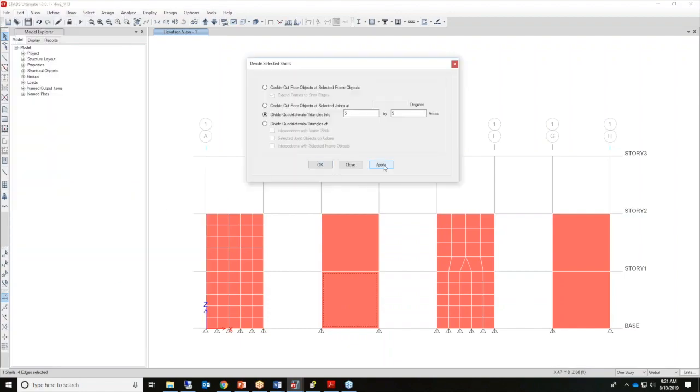And I'll do the same for this one, but I'm going to make a little bit of a change here on top. I'm going to make this 4 by 4. So here we have a situation with some mismatched nodes. That's a very common question as well when it comes to meshing: what happens to load distribution if the nodes aren't exactly matched? We'll get into that in this example. Here we'll do the same thing, 4x4 on top, 5x5 on the bottom.